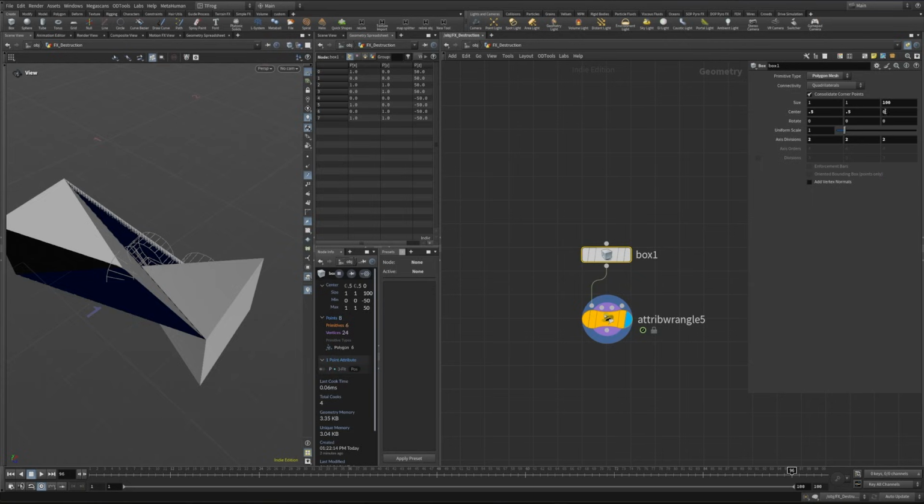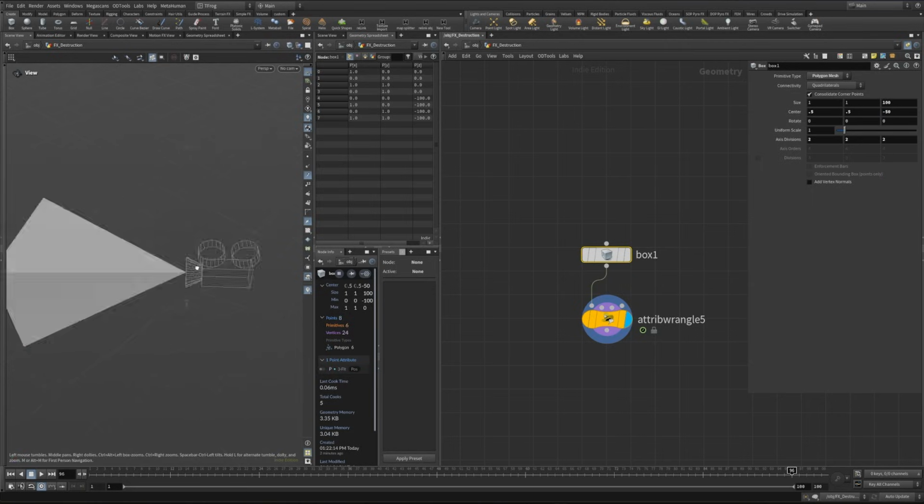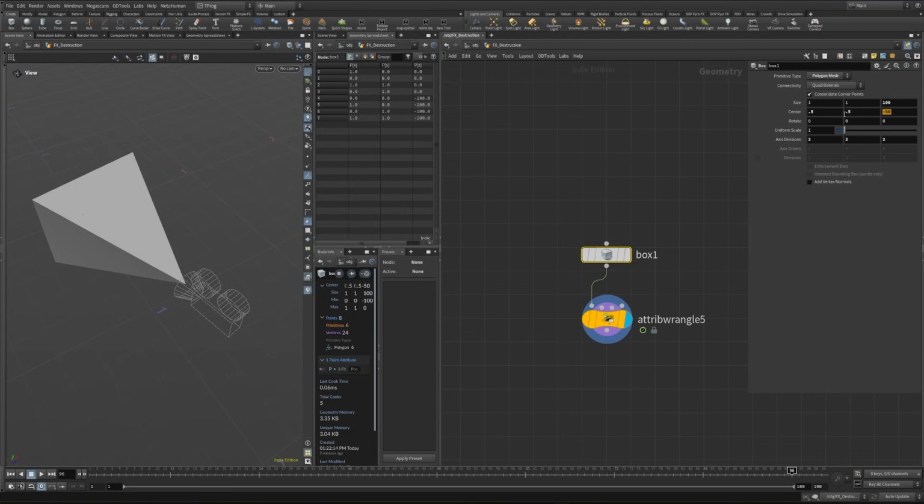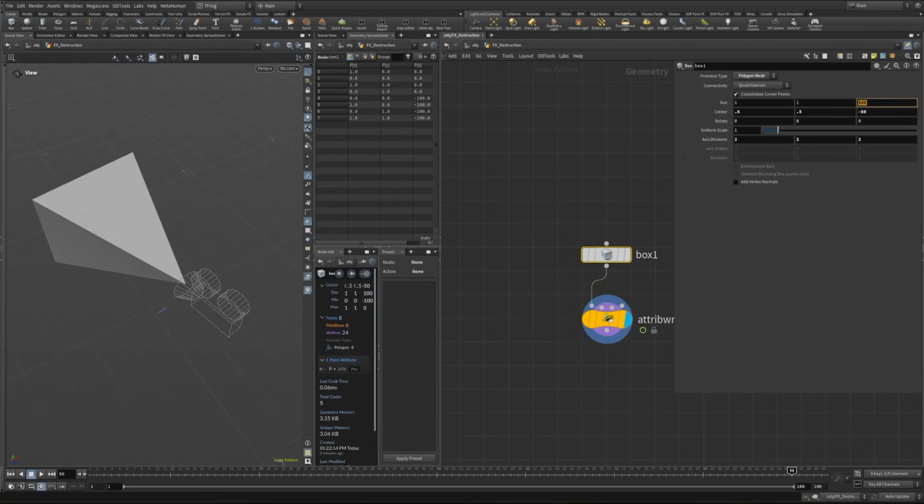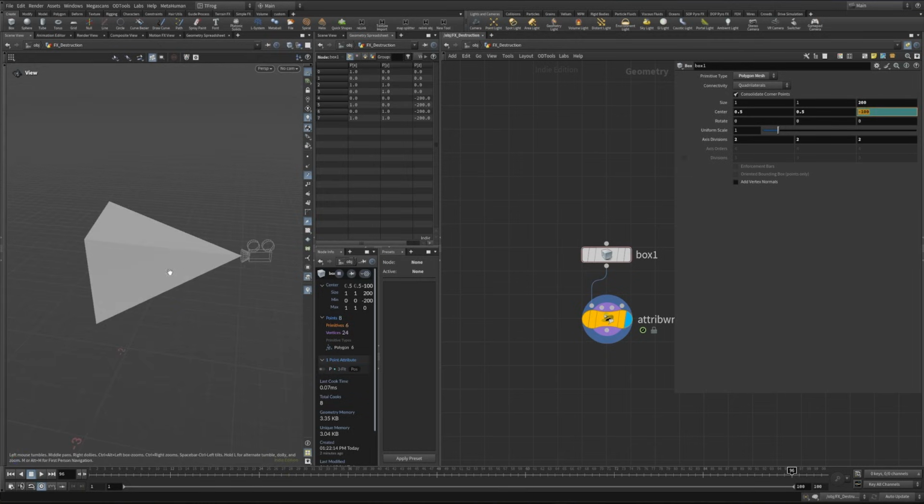So we have to copy this parameter, and for example, if we type -50, you will see it's correctly here. So we always have to have the half of this value here, but also inverted. So let's paste the value in here, paste relative reference, divided by 2, and also a minus before. Now if we change up the value here, for example to 200, you will see everything is working now.